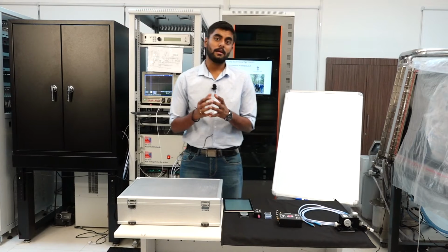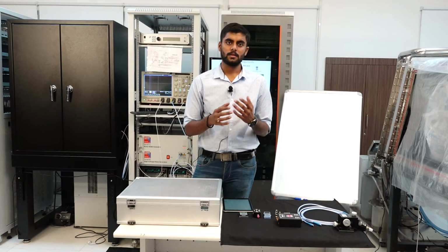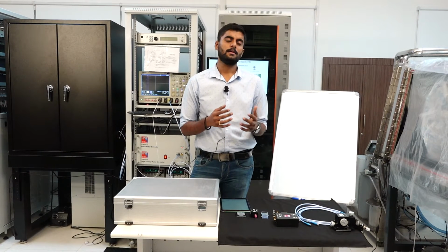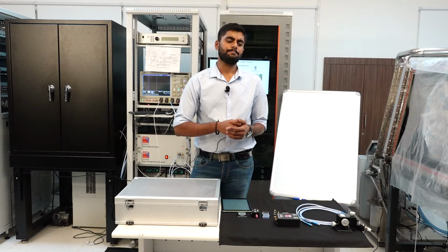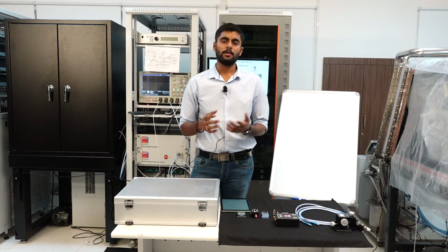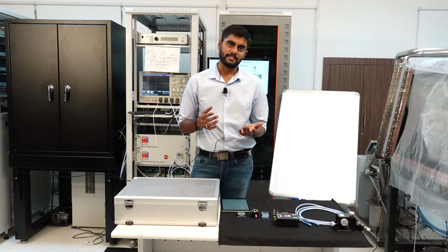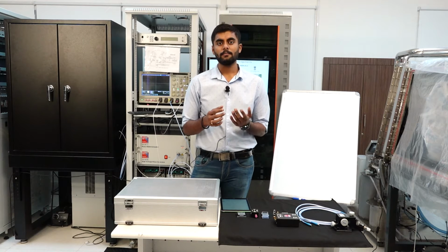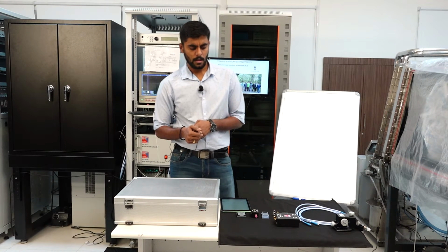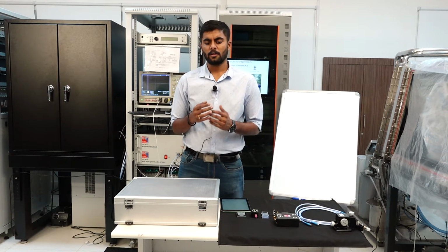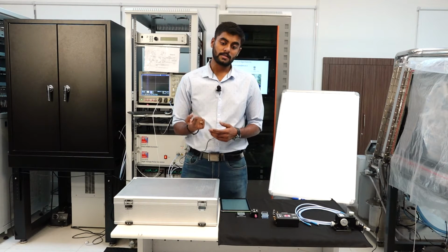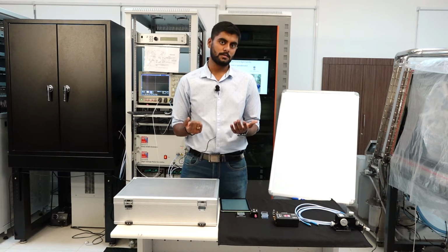So now there are multiple characterization techniques that get involved in the microelectronic reliability. So one is called DC reliability tests. So basically, in a DC reliability measurement, you apply a DC signal to the different contacts, and you can choose the contacts appropriately as you want. Then there is something called pulse characterization. A pulse characterization involves applying pulse voltage signals to the device under test, again to different contacts. Now there are some important considerations when you talk about pulse characterization techniques over a DC characterization technique. So one is, as you can understand, a pulse characterization technique involves a lot of waveforms.